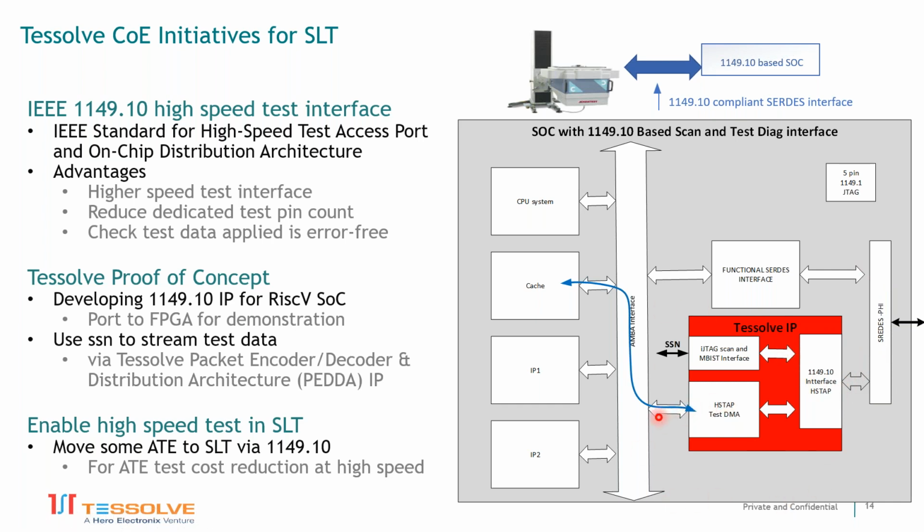And this is on die. You're burying this IP on die. Yes, the IP is on die. Exactly, that IP has to go on die. So you dual purpose your USB interface. Some companies have an issue with that, because USB interfaces are hard enough to design anyway, and then having it for both functional mode and test mode. Some people think that might be an issue, but we don't see it as a major issue.